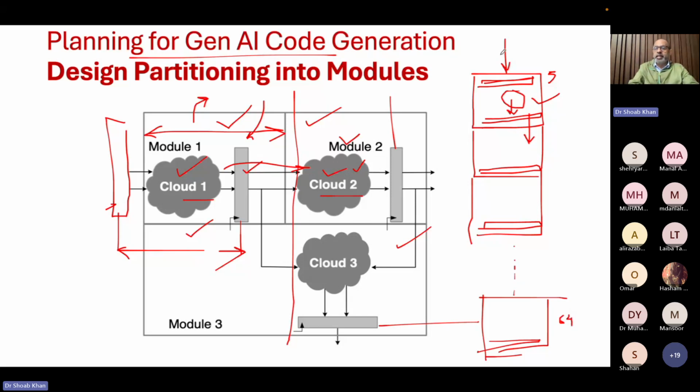But the good thing is, every clock cycle you can process one block. So every clock cycle you get a new block. The previous block goes here, the previous to previous goes here. So it just keeps on shifting, and your throughput would be one complete block in a cycle. So every cycle you have a block. This is if you are independently processing a block.